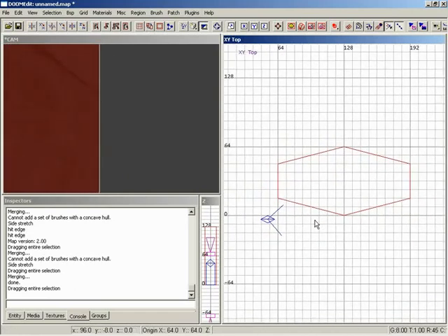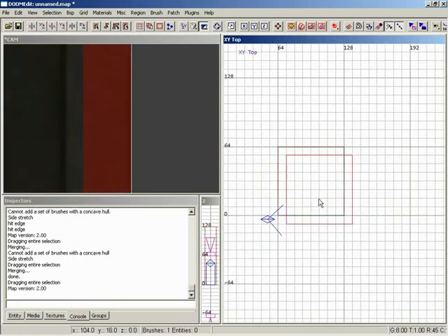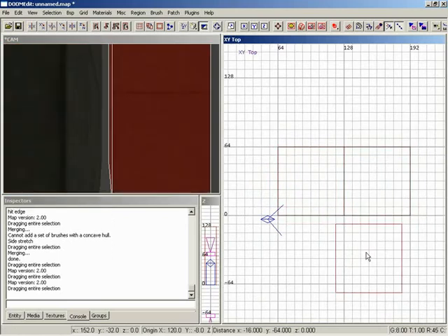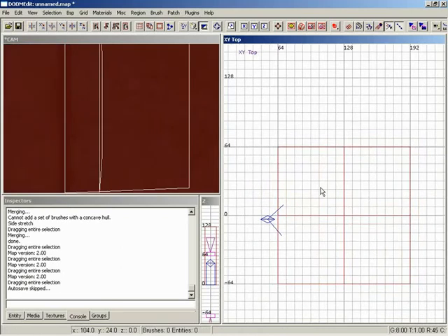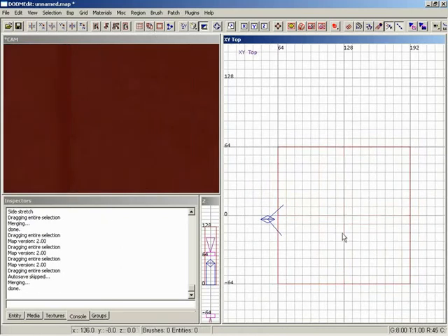Okay. And this is really good to point out as well right now, Logan: you can merge multiple brushes together, not just two like we've been doing here. Right. For example, if you were to take first cube, second cube, third cube, and as long as the result is going to be convex, it'll work. All 4 merge, and then all is good.